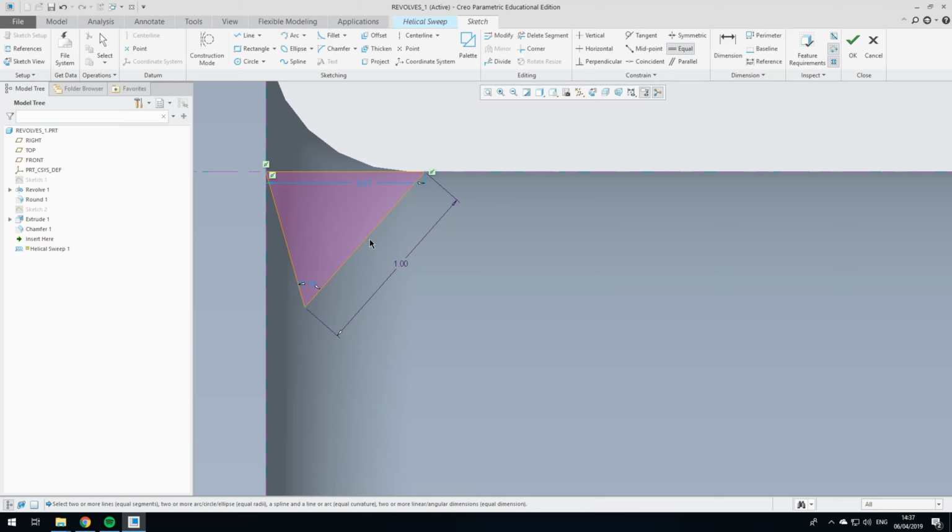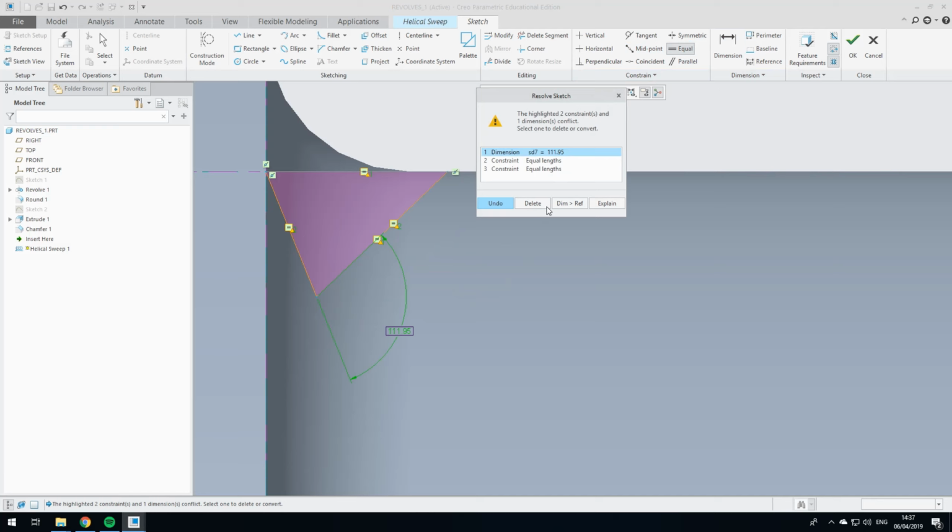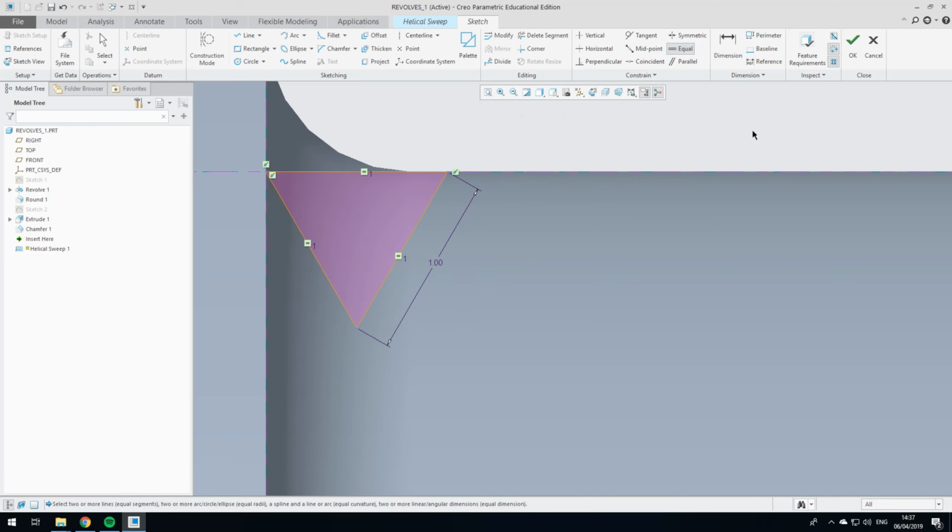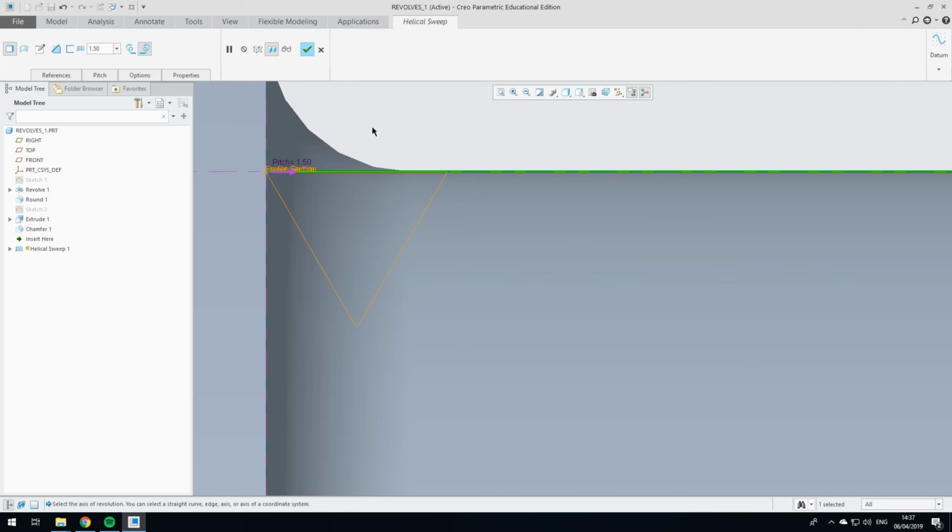So these will now say these are all of equal length. So I left click the face that I want as my dimension, click the target one, hit the middle button, and then same again with this one. And if you notice, it will automatically change that angle. Oops, I clicked on it by accident, sorry. It will automatically change this angle. Now I've asked for equal lengths here, so if we delete that because it thinks I did that, that's now an equilateral triangle in there.